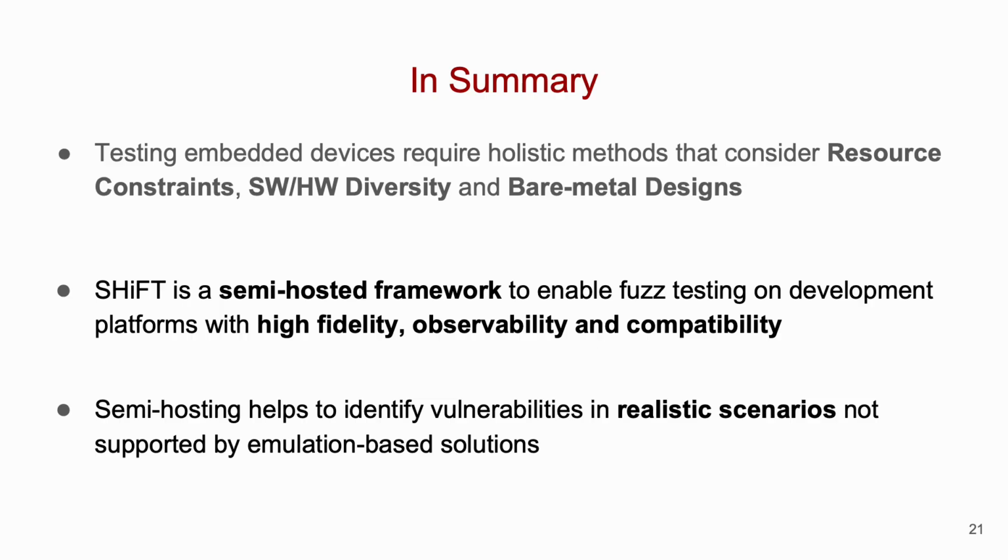In summary, SHiFT shows that fuzz testing embedded applications requires a method that considers the resource constraints, diversity of software and hardware, as well as bare metal nature of embedded devices. SHiFT proposes a semi-hosted framework that enables native execution of target binaries on the MCU, achieving high fidelity of hardware, observability of faults, and compatibility with peripherals. As such, semi-hosting provides a useful alternative to identify vulnerabilities in realistic settings that most emulation-based frameworks seem to miss.